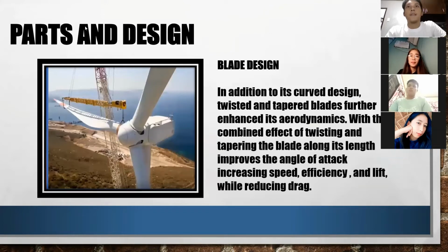Blade design. In addition to its curved design, twisted and tapered blades further enhance its aerodynamics. With the combined effect of twisting and tapering the blade along its length improves the angle of attack, increasing speed, efficiency, and lift while reducing drag.